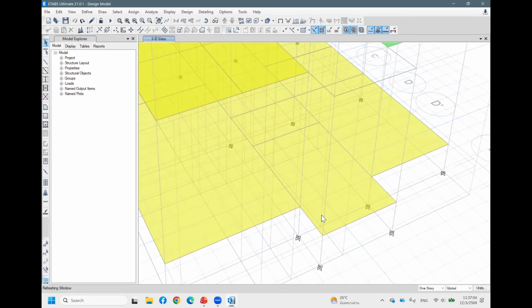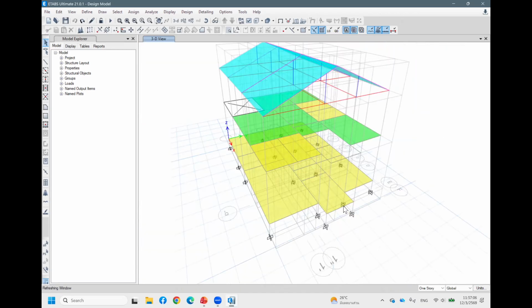This one is for the stair channel. So the stair, I don't recommend you analyze it in the tab. You can do it, but I think the load is quite complicated. If you don't know how to assign correctly, the load will not transfer like we want. So I will introduce the method to make the load like you want.